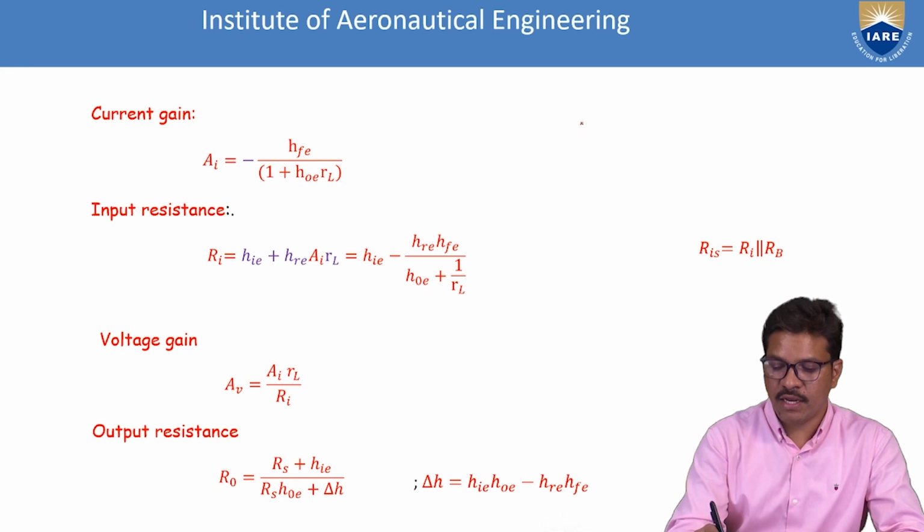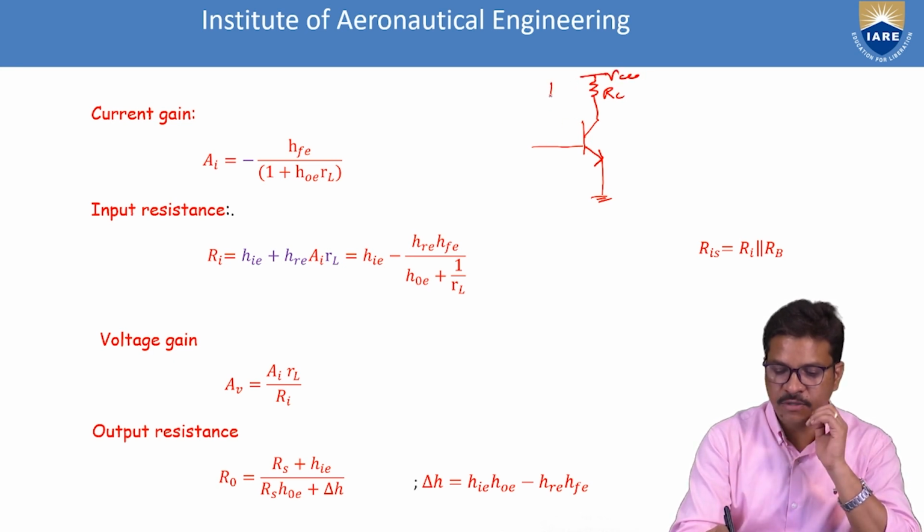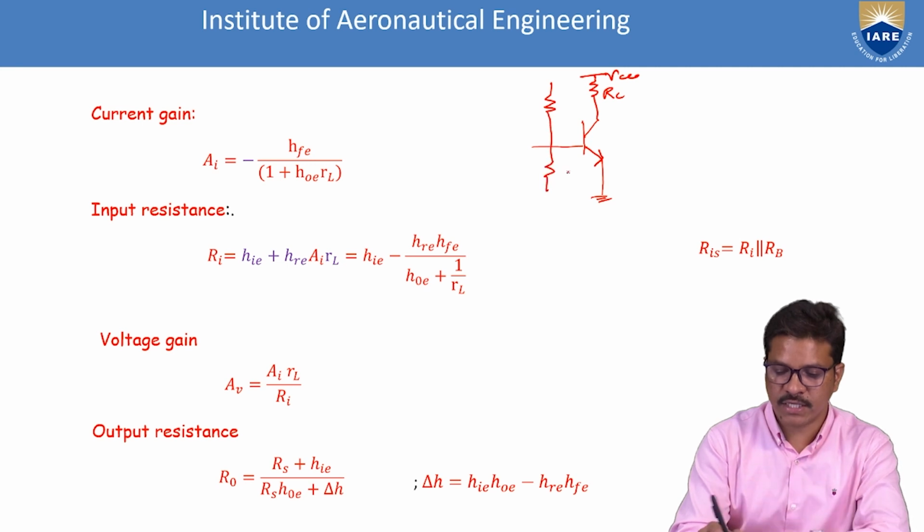If you take, for example, a common emitter amplifier, it means providing the configuration and proper biasing with resistors and supply voltages, and the best bias is the voltage divider bias. We provide this kind of bias, give some input voltage and measure the output voltage.